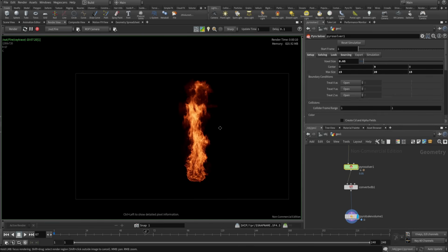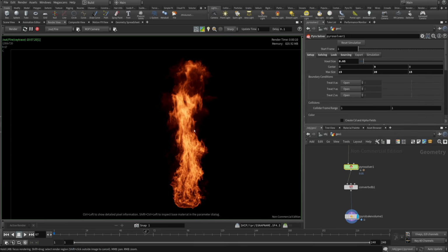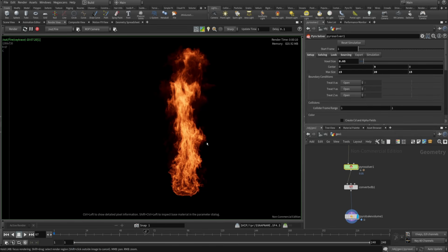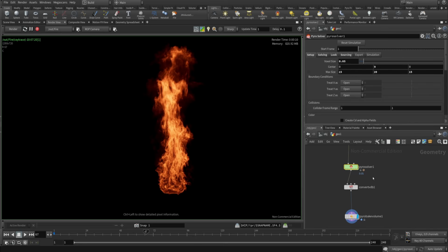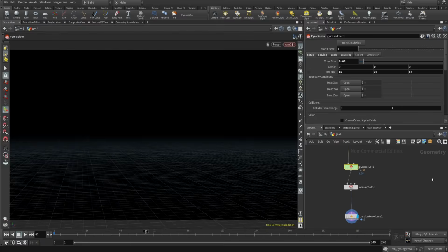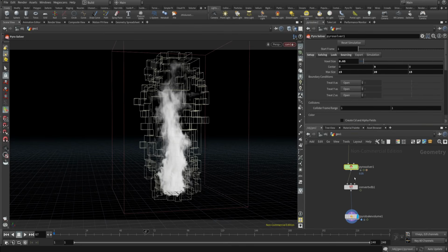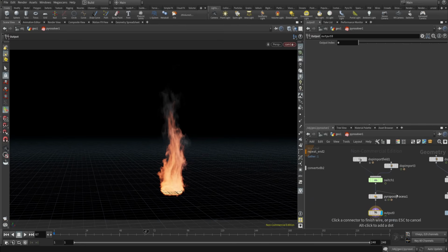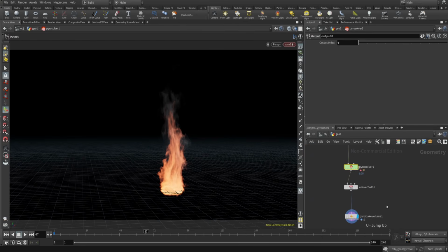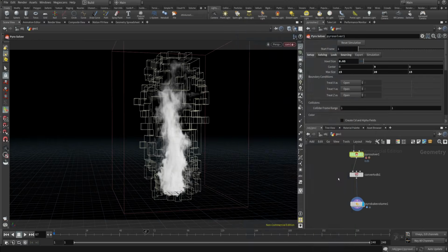Okay, that's good. One thing that is so important about rendering fire is using motion blur. It's much more important than using motion blur in the explosion. I need to have velocity data. Currently, with a Minimal Solver, we don't have any velocity data, so I need to open this digital asset, dive inside, and connect the Pyro Post Process to this node. And now we have velocity.